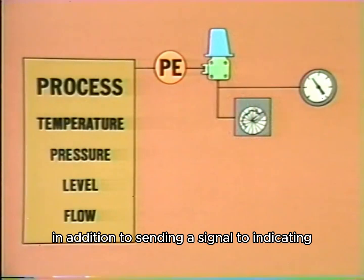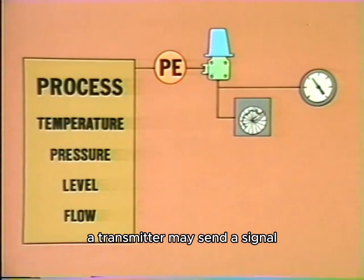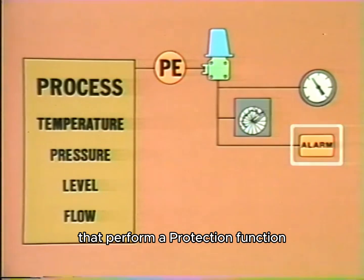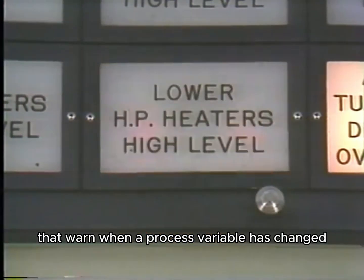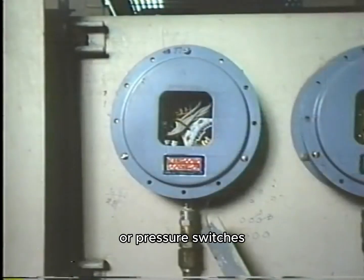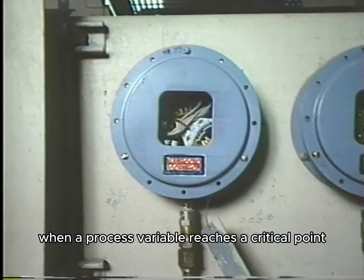In addition to sending a signal to indicating and recording instruments, a transmitter may send a signal to associated instruments that perform a protection function, such as alarms that warn when a process variable has changed beyond desired limits, or pressure switches that bring in a backup safety system when a process variable reaches a critical point.